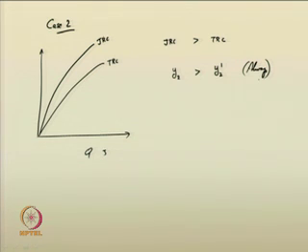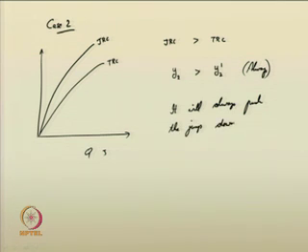What does this create? For such cases, it will always push the jump downstream. We have seen that when the jump depth is greater than the tailwater depth, the jump is pushed downstream, so you can use control measures appropriately to provide jumps in such situations.